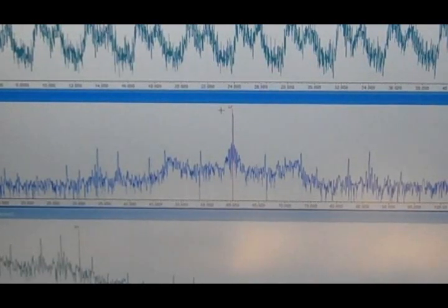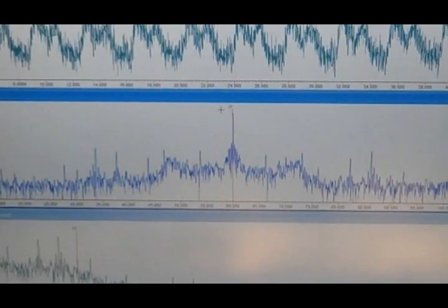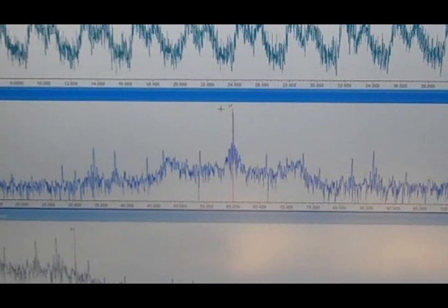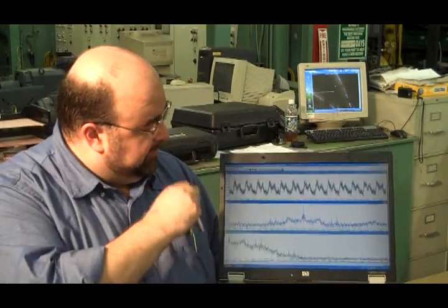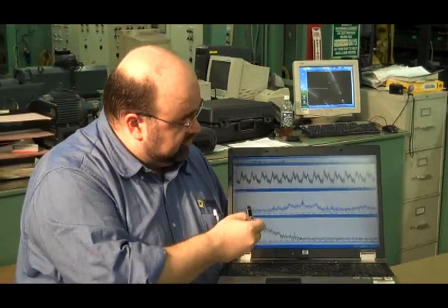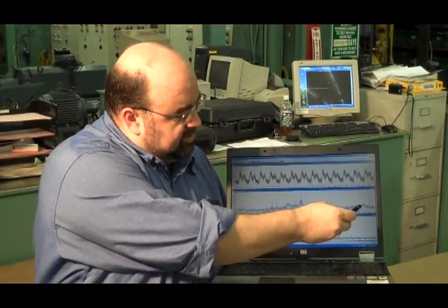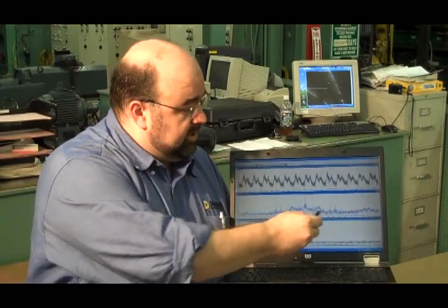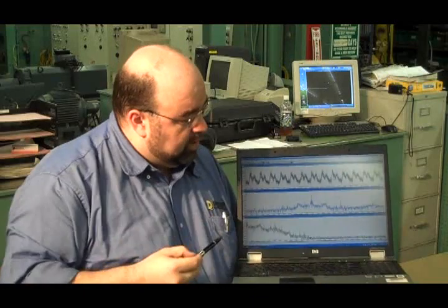Now I do have a screen up showing what the online testing is capable of doing. On here, this is actually from an electric motor. The call was noise, and when we went out there to take a look at it, you can see the top screen here is RMS current. That's the actual current the motor's seeing across 60 seconds. This is what's called a fast Fourier transform of my current across 120 hertz, and this bottom one is called demodulated current. This is not worth that much.